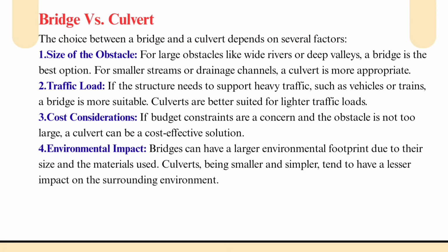Now the next question that comes to mind is when to provide a bridge and when to provide a culvert. The choice between a bridge and a culvert depends upon several factors like size of the obstacle, traffic load, cost considerations, environmental factors and many more. So we'll check these points one by one in detail. The first one is the size of the obstacle. For large obstacles like wide rivers or deep valleys, a bridge is the best option. But for smaller streams or drainage channels, a culvert is more appropriate.